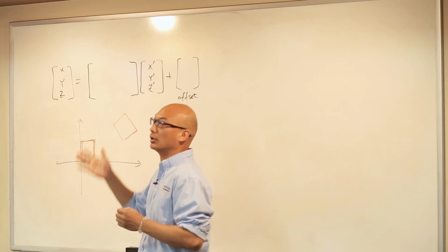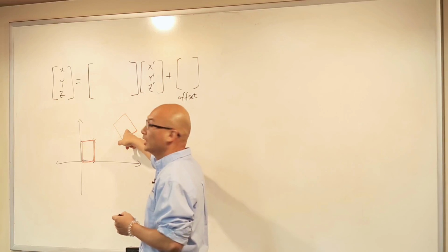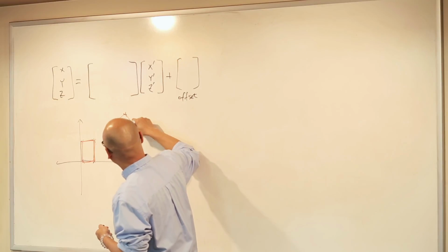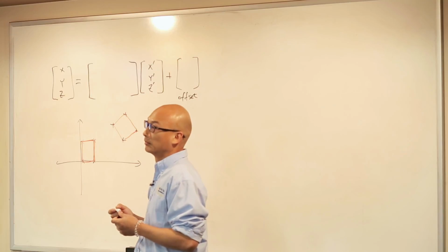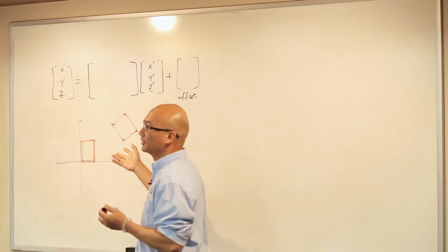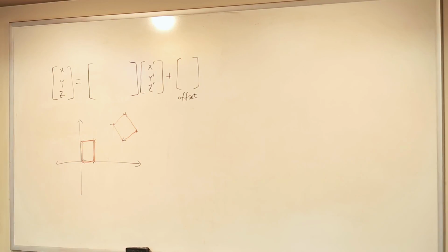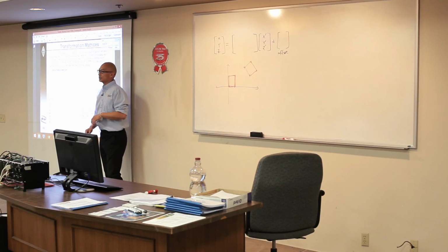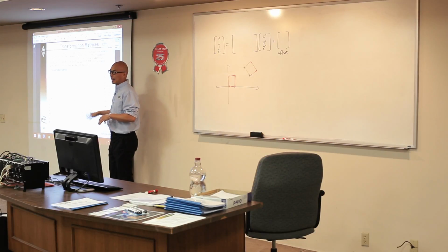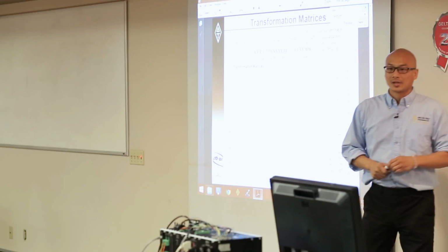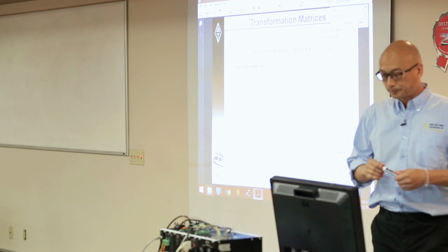And then put that in your motion program. The same thing here: you have to calculate this by yourself and then put it in the motion program, right? But since they are the same pattern, we provide a tool that lets you just input the transformation with the rotation, with the scaling, with the offset, and now we will execute this for you directly. Okay? So that's the first thing to understand.